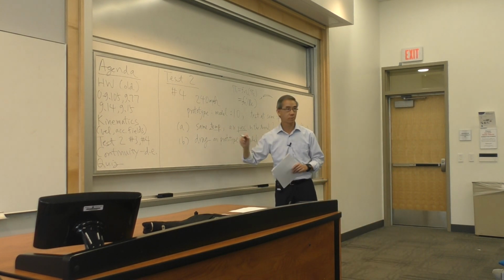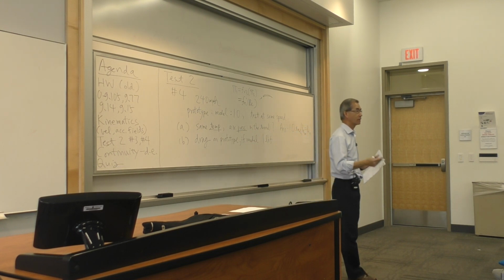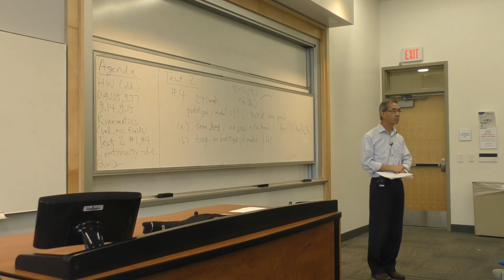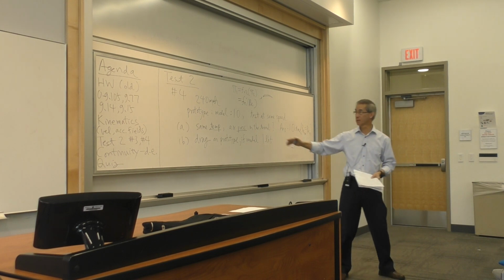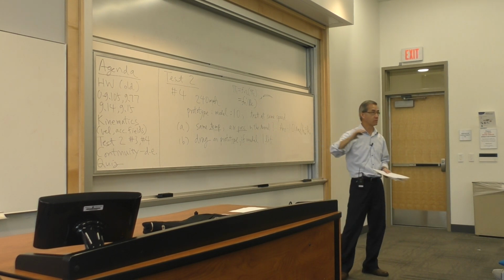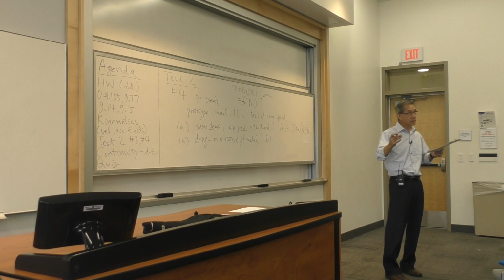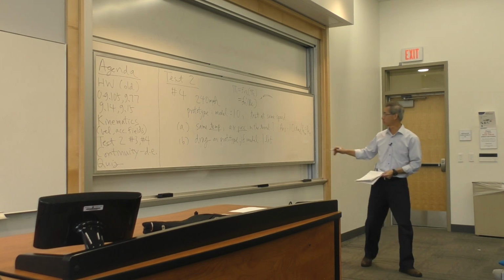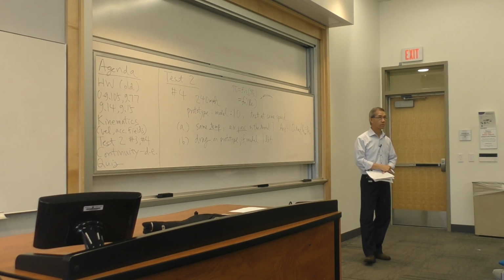With no change in temperature, you will have to use ideal gas. That's maybe the missing link, but it's meant to be a pretty simple problem. You don't let me change the velocity, and you don't let me change the temperature, and you shrink the model by 10 times. From ideal gas, I have to jack up the pressure in my tunnel by 10 times to match the Reynolds number, no more, no less. This is how you do part A. Do you understand what I'm saying?